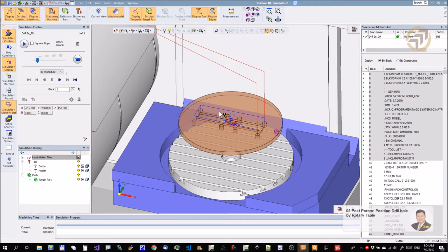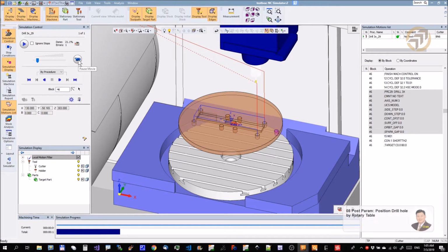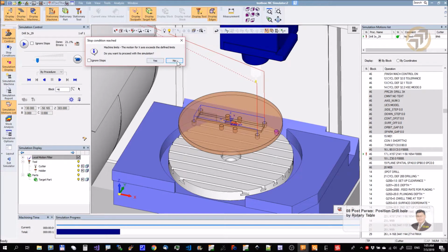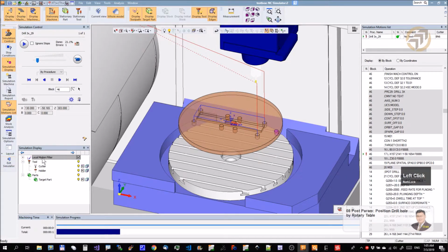Okay, I'm drilling 4 holes here. On the left hand side, these 2 holes should not have a problem, but the right hand side will reach the X plus limit. Let me show you. If we use the default pose parameter, we will have this problem, because the default pose is moving the XYZ to position the hole, and this causes the limit error. And how to solve this one?